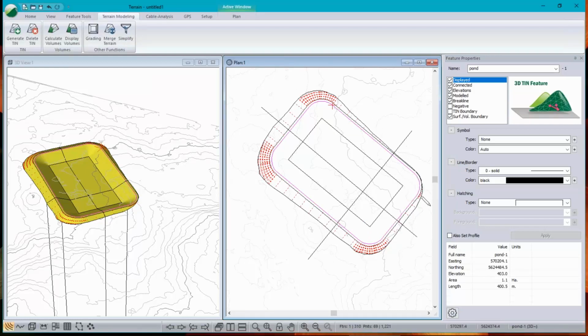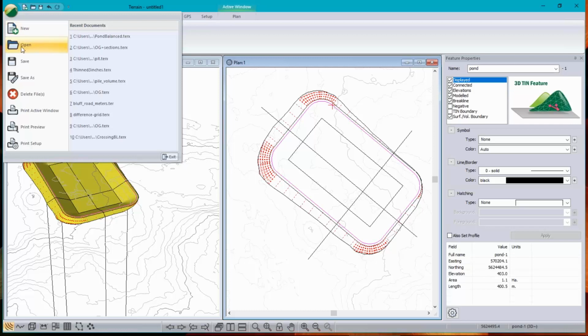Moving on to the next part of our demonstration. I'd like to see a CutFill map. Where is cut, where is fill, and what does that look like? So this is fairly straightforward. Once you have two surfaces, the CutFill map measures the difference between the two surfaces, whether it's positive cut or negative fill. And we do that like this.